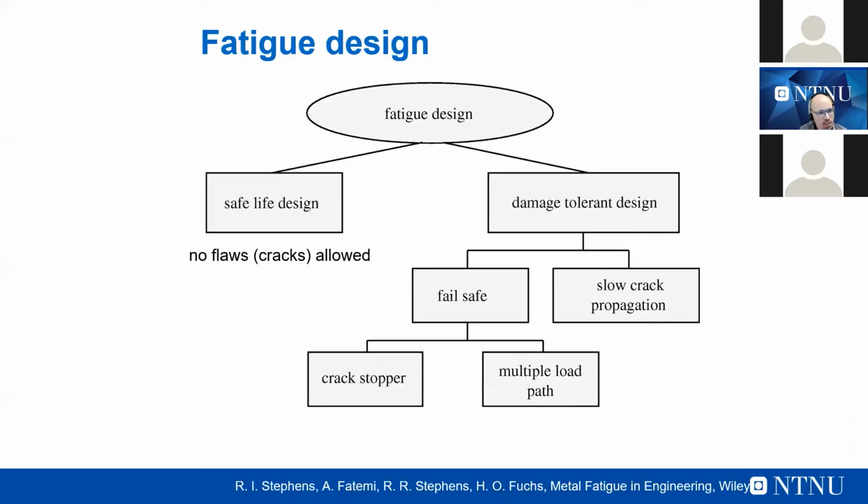We have different approaches for fatigue design that we can consider. But of course, for additive manufacturing, safe life design, where you have infinite life, is not an approach that you can apply, because mainly you always have defects present in your component. So you have to survive with the defects and understand how the defects interact with the fatigue behavior of your component.